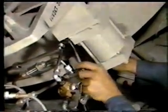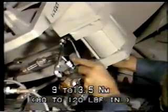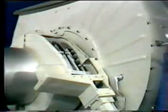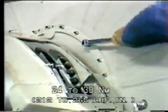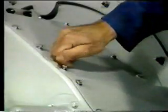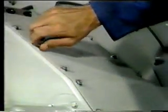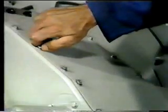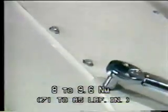The pressure lines can now be removed and replaced with the actuator lines. Torque the securing nuts to 9 to 13.5 Newton meters. Next, remove the gauge and replace the two nuts. Torque the nuts to 24 to 30 Newton meters. Carefully replace the housing cover. Tighten the bolts finger tight to allow enough play to insert all of the bolts. Torque the bolts to 8 to 9.6 Newton meters.